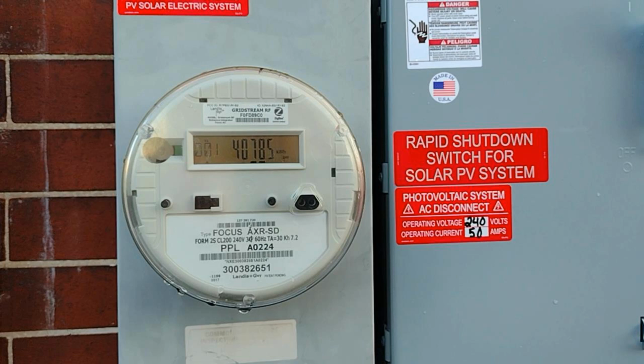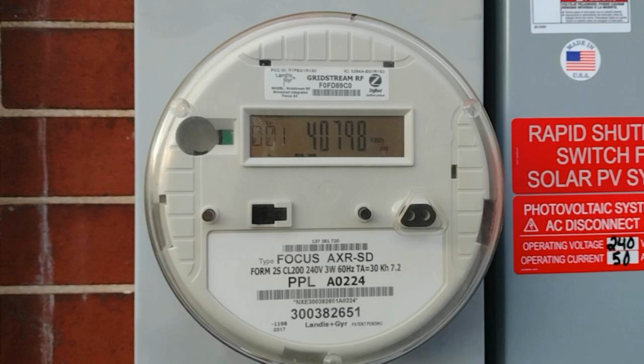Okay, so the first number here, this is your power meter. This is your lifetime supply since the meter was installed. Always goes up, never goes down, like an odometer in a car. To get your daily use, you would come out at a certain time in the morning, read the number off of here, come back the next day, read the number in the same location, and subtract the difference. That's going to say how much you used over one day. Same thing for a week, same thing for an hour, whatever you're trying to read. This is the number that they use for billing. So this is simply your power meter.